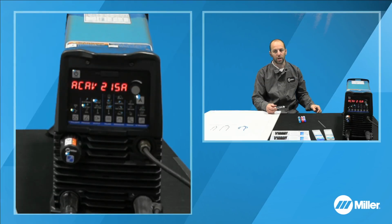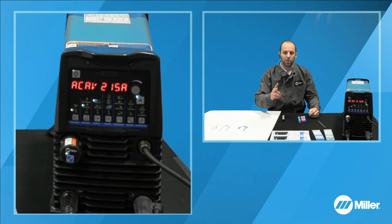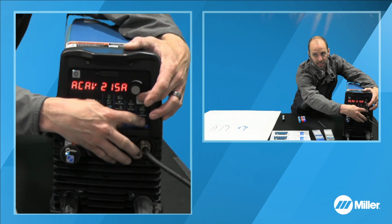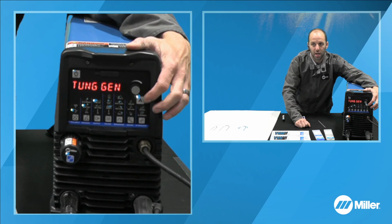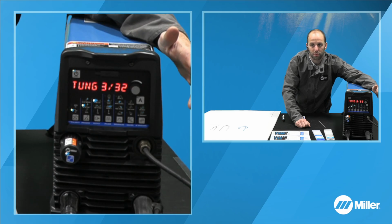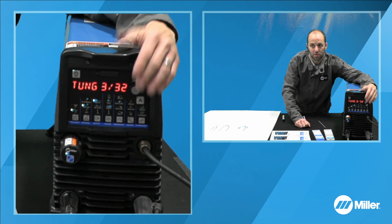So I'm going to go through here quick and just show for the audience how we make those selections on the Dynasty DX interface. We look at 2 different buttons here: the A button in the upper right-hand corner and then also the second in, which is your gas button. We're going to push those two simultaneously and just do one quick press. And you can see here there's different tungsten selections, both metric equivalents and our US variants here.